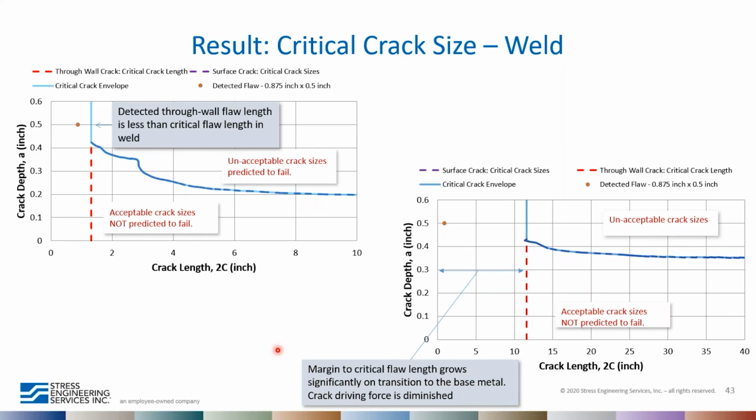So that really explains to us why the crack which grew or initiated and spanned that weld did not progress further into the base metal. And that gave kind of a general indication that the component was not under imminent failure concern. And so they were able to put a clamp on the component and plan a repair at a later time.